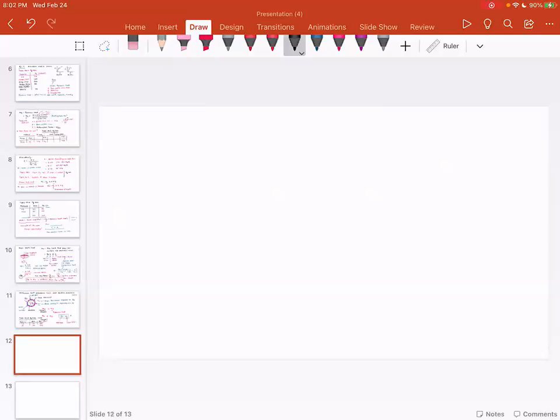So if you observe a gear, what are the major failure modes? Gear could actually fail in bending. Gear could fail in surface material removal, which is called pitting. Gear could fail in large chunk of material removal because of the heat, which is called scoring.